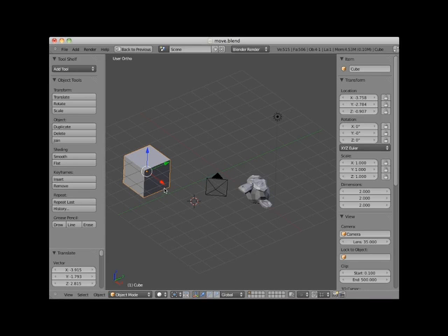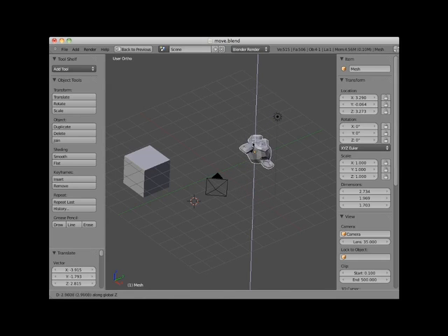It is also possible to constrain the translation to a specific axis by first selecting the object, pressing the G key or the Translate button, followed by either the X key, Y key, or Z key. For instance, here I will select the monkey object, press the G key, and then press the Z key. I'm able to translate the monkey object anywhere along the monkey's Z axis. To confirm the position, I left-click, which ends the translation.